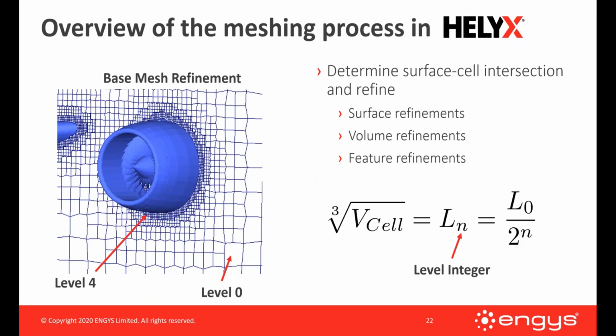If the cell locally is bigger than that geometric component that we want to capture, then it won't snap and refine. It won't capture that small geometric component. So this goes back to the whole dirty CAD concept. If we have these small features, we could spend time to remove them from our CAD, or if you just use larger cells than what are on the CAD, then you can often just defeature the CAD itself during the meshing process. So you need to be aware of that also while you're meshing.